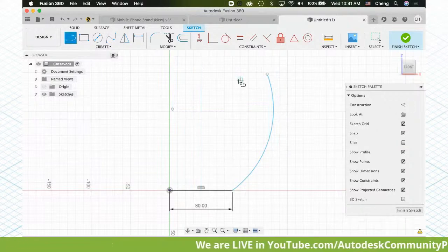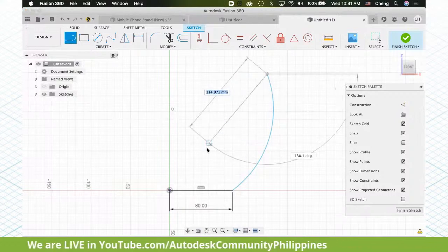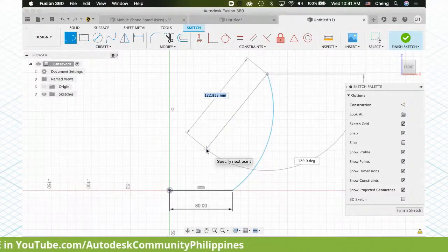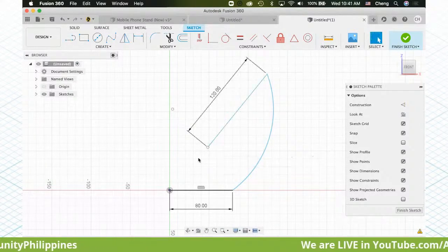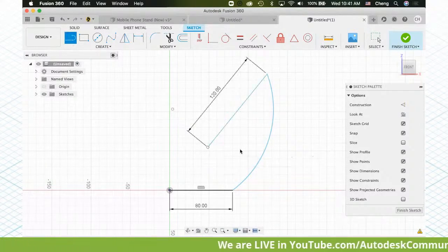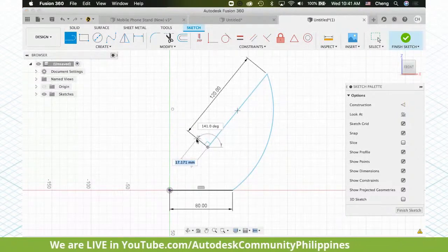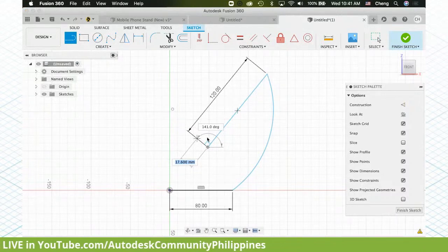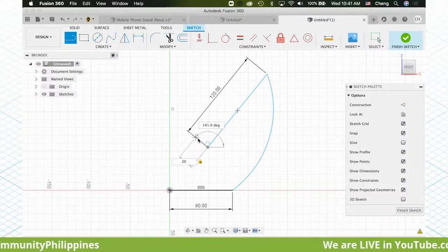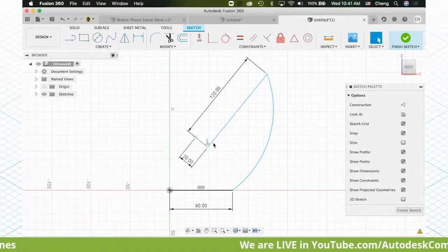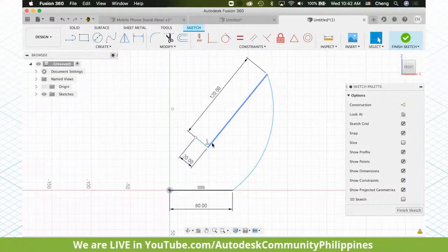Next, I need to create the mobile phone resting position. I am building the resting position. The length here is 120. Okay, the next one I am building is the mobile phone resting position, which is perpendicular. You will see that automatically it will draw a perpendicular sign, to be 20 mm. Do you see this T sign appeared? So this is now being shown as perpendicular.